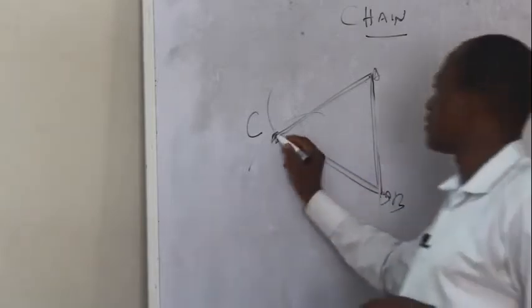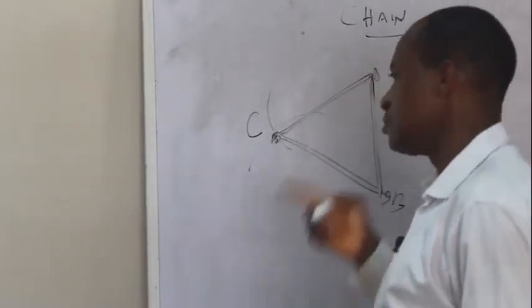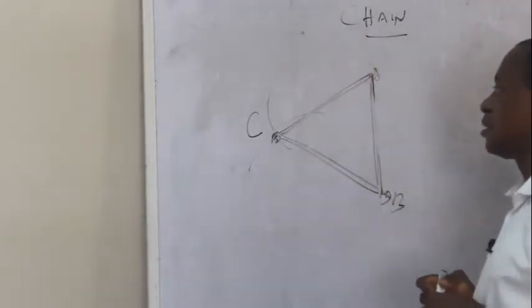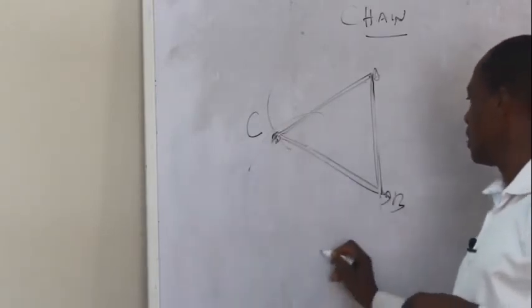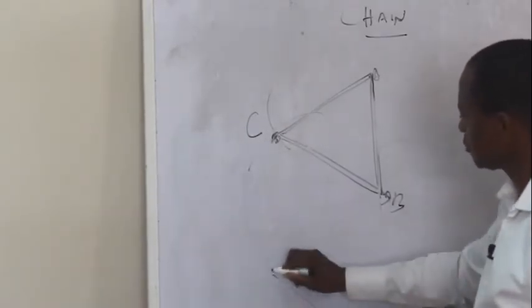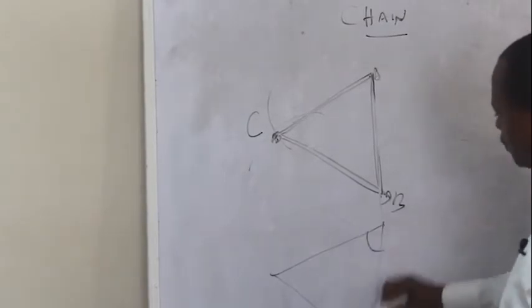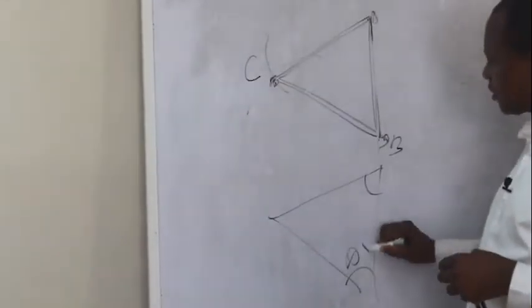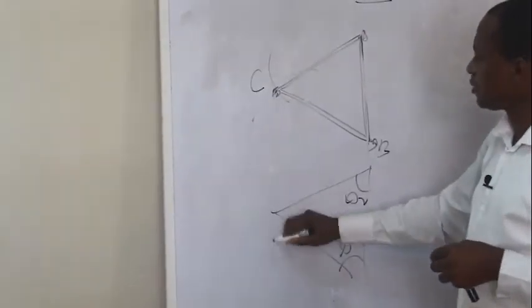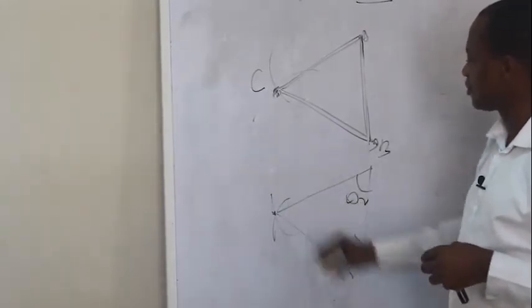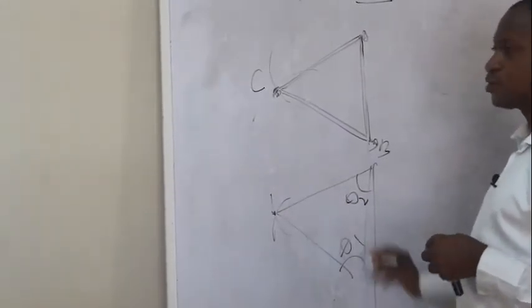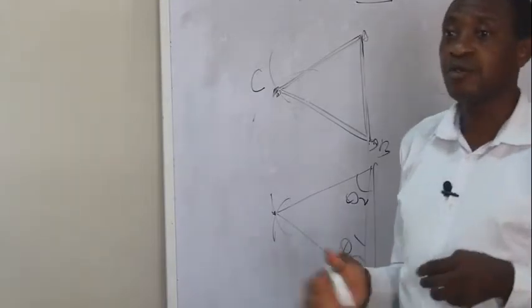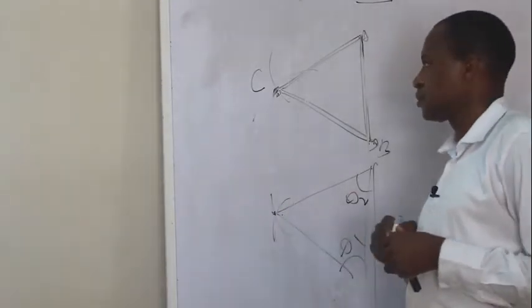So with that, we can determine this position. And there also I mentioned that you can fix this position by intersection. That is when you can take angle from here, theta 1, theta 2, and you can fix this point. Once you have known this distance, you can apply a sine or cosine rule to determine this position. That's one.